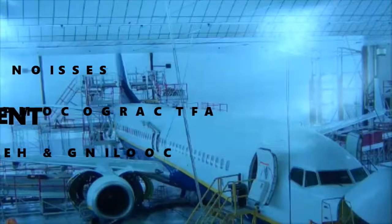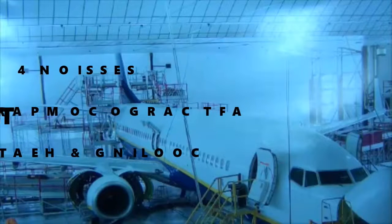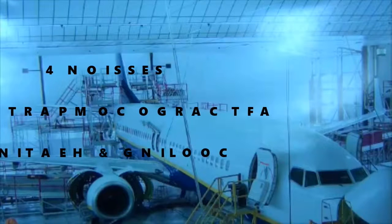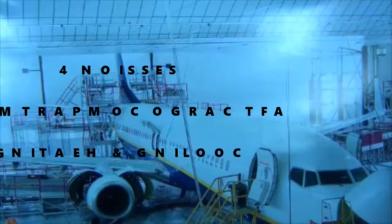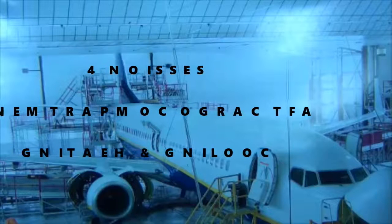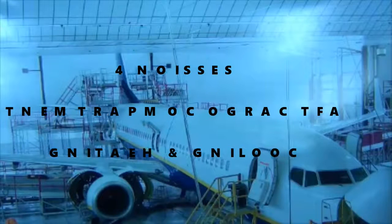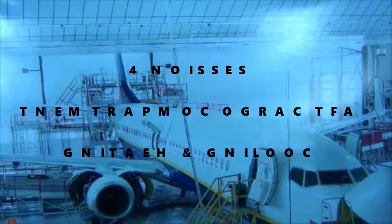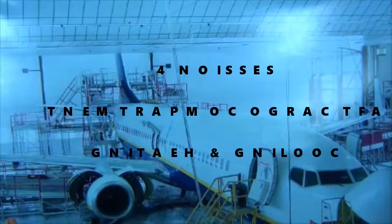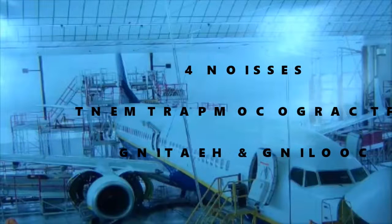Okay, so there's really not much to it. I just mentioned you're still going to have controllers, right? So you have a heating controller for the aft cargo compartment for the heating part, using the hot bleed air, the trim air, and then you've got your isolation valve and your extraction fan. Okay, so that's pretty much it. And of course there are diagrams that help you see what they look like, but if you've seen fans before, it's pretty much a fan's a fan.